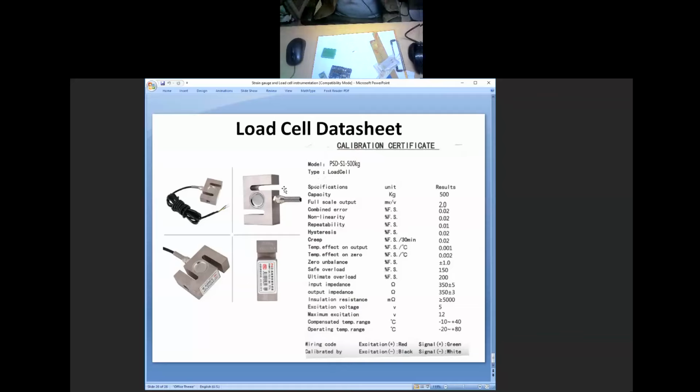And finally, the last one is here with me. This is what we call the beam type load cell. If you look closely here, you see here is one arrow. It is going in the downward direction. It means whenever you try to load it, it should bend in a downward direction, in the direction of the arrow. Then the positive result will come. If I reverse, of course it will work, but your result will come in the negative. So that's why they give a convention. It's just a 40 kilo capacity, and this load cell is a 1,000 kilo or 1 ton capacity. So here, me and my students, we are involved in all these sorts of instrumentation and activity.